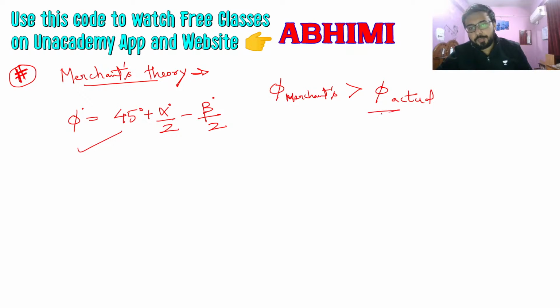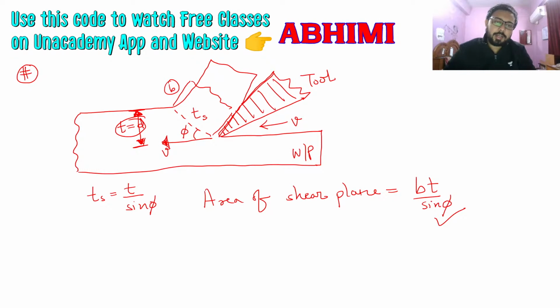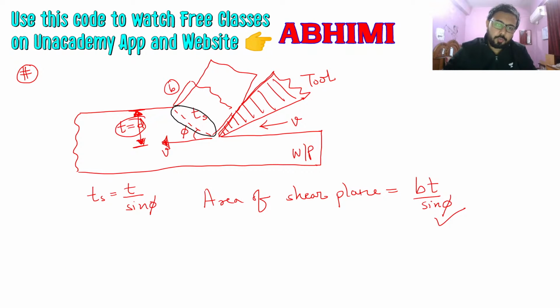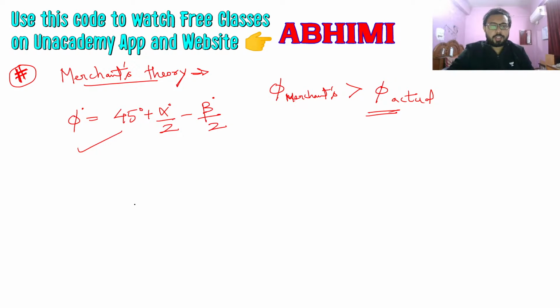And if the shear angle is greater, then you can see that your shear plane will be smaller, because the area of the shear plane is bt by sine phi. So if phi is greater, then this whole term will become smaller. This will lead to less cutting force, less power, so overall less energy consumption, less power usage, and therefore less temperature. So Merchant theory is giving you minimum energy usage, minimum power usage, and minimum temperature.